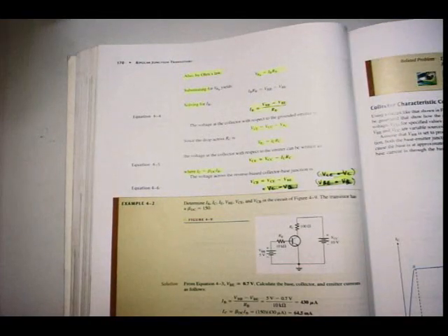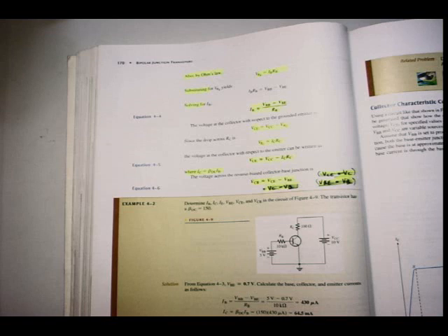Now if we turn the page, also by Ohm's law, I've seen that VRB is equal to IB times RB. Then substituting for RB, IB times RB is equal to VBB minus VBE, and then solve for IB. So all that they've done here is they've combined the formulas. IB, and I've combined then Kirchhoff's law on top, VBB minus VBE to determine the voltage drop over RB, and below the line RB, which gives me my Ohm's law. The voltage at the collector with respect to the grounded emitter, remember VCE.